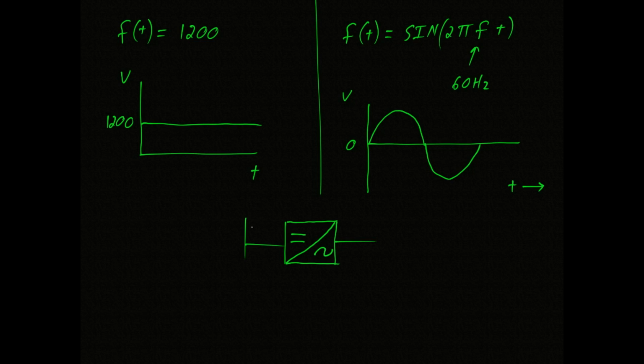Let's put the battery back in and see how it operates. We said that the battery provides a backup power source. That means power can flow from the battery and get transferred from DC to AC. But the battery also needs to be charged, so when power is available, say from a solar generator or hydro, the power can flow back this way through the converter to charge the battery. So this device can be a DC to AC or an AC to DC converter. Later on, I hope to talk about the technology that's inside this converter. It's actually computer controlled and very sophisticated in what it can do.